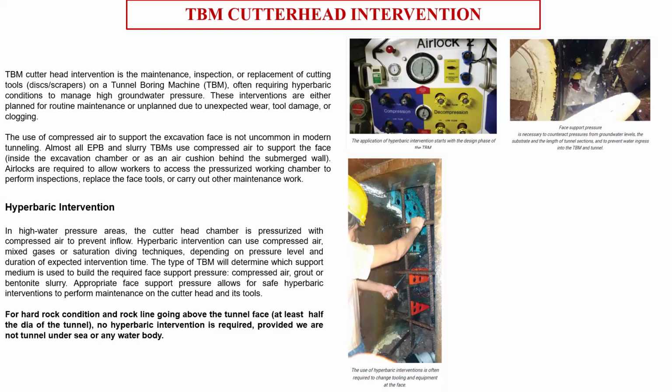Sometimes the circle becomes elliptical, because one side may get some thrust, so it becomes an elliptical shape. So I have to compare this with the tolerance segment by segment, make a comparison chart, and then decide which segments have gone out of deviation. For the deviated segments, I need to take some additional precautions to make the segment durable, in terms of design life for durability.